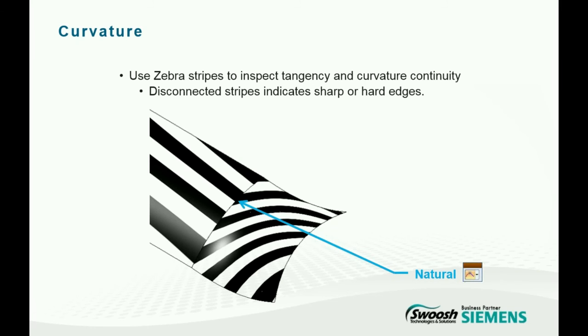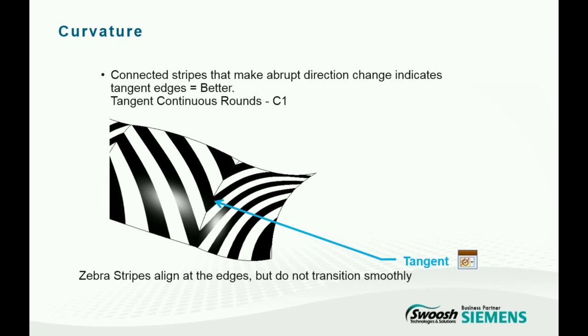So when you apply this tool, you can quickly see that when the transition between the newly created BlueSurf and other surfaces is natural, it's actually breaking the zebra quite aggressively. If you go with the continuity C1, which means tangency, it's still breaking the continuity of the surface, but you can see how they come together at the same point, pretty much.